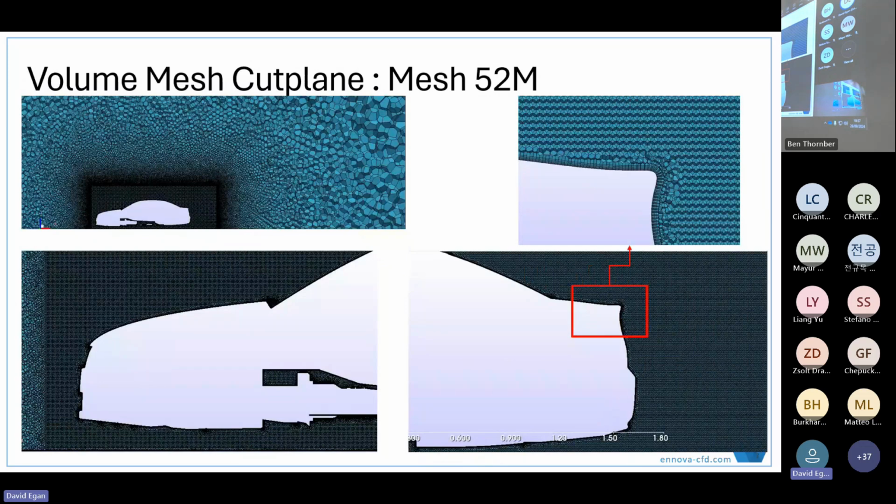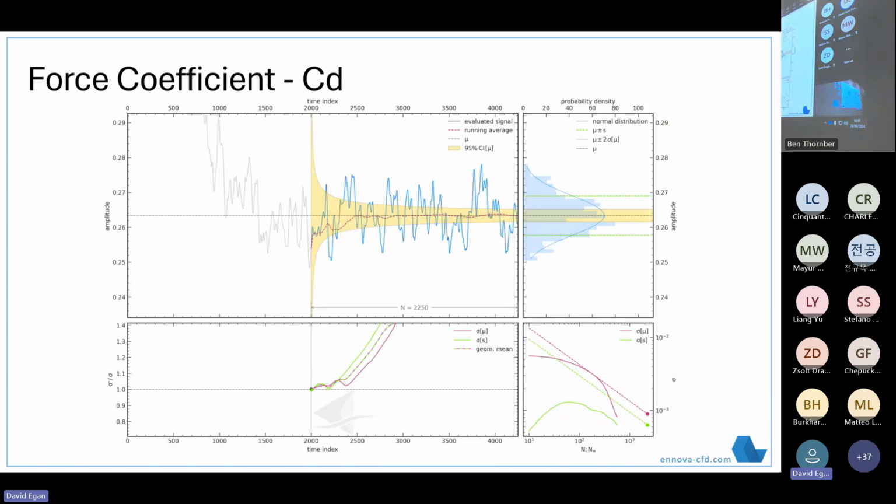That was what the mesh looked like. We tried to do the refinements similar to what you have in the committee mesh, maybe a little coarse, not quite so many boxes. One of the big differences of doing the mesh this way is that you have a very gradual and gentle growth rate in every direction. We don't have the 2-to-1 transitions that the Octree approach has. So typically, because of that, people often use the polyhedral approach in acoustics, things where you have waves. Maybe not so much in subsonic external aero, but just typical convergence results.